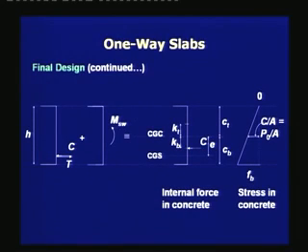In this figure, we are studying the stress conditions. h is the total depth of the slab. First, at prestressing, the compression is at the same location of the CGS. Then, as the self weight acts, the compression moves up from the CGS, and it has to be within the kern zone to avoid any tensile stress in the section.